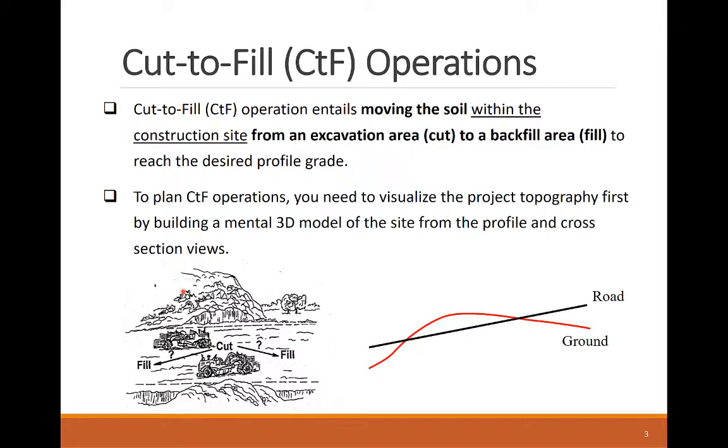So what is a cut-to-fill operation? Cut-to-fill operation is the process of moving the soil within the construction site from a cut segment to a fill segment to reach the desired profile grade.